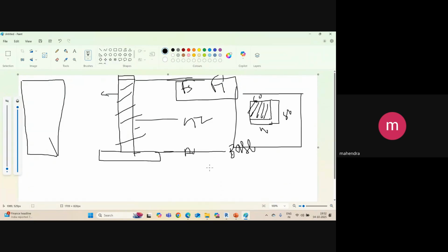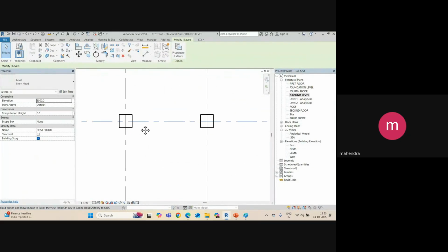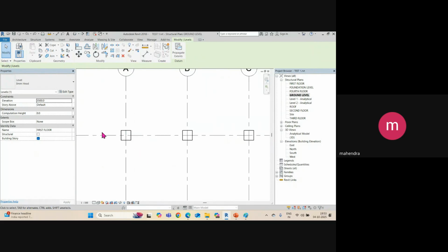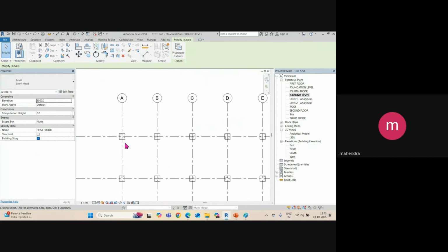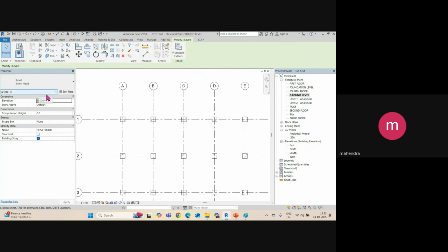Then in this direction, I will add this at the side face here, building side. And at the center or middle, this is 800 by 800 and the remaining 600 by 600 column is going up. Okay, so these three criteria you can model here. Let's see, we can add here. What I do, I will add three different conditions, one condition here, one condition here, and one condition here. So I will add a separate column here.